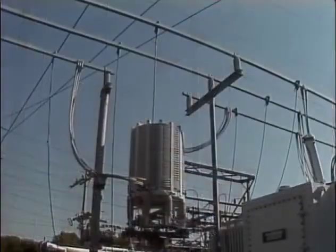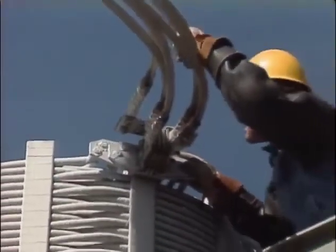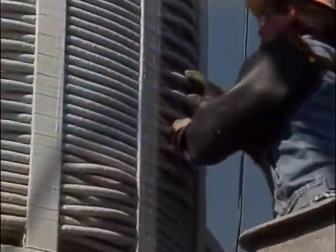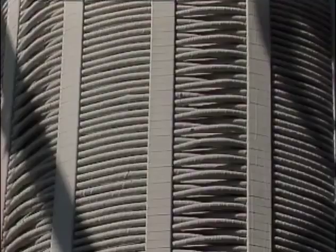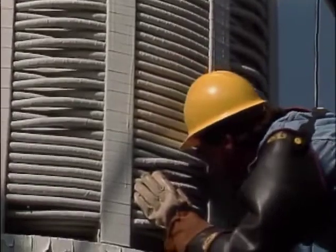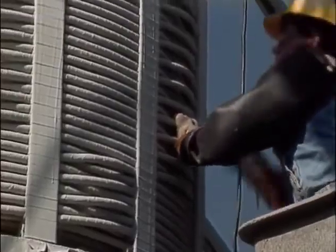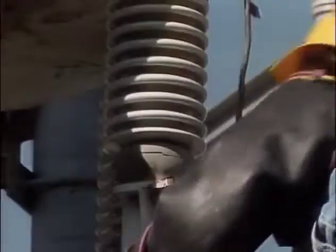With the reactor grounded, it can be safely checked for damage or signs of problems. The connections to the reactor are checked to make sure they're secure and in good condition. The coils are inspected for signs of arcing, accumulations of debris between the coils, and other unusual conditions. The coil supports are checked for cracks or chips that may allow current to arc across the coils. If arcing is evident, or if the coils or supports are damaged, the reactor may need to be taken down and overhauled or replaced. The insulators are checked for cracks, breaks, and signs of tracking. If an insulator is damaged, it may need to be replaced.